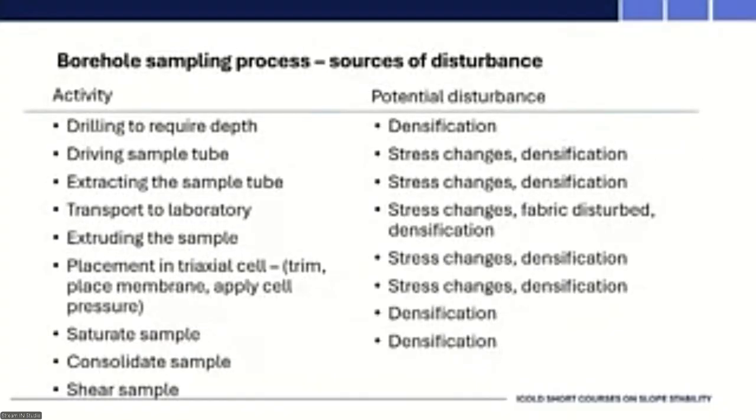The activities that we typically encounter when we have to sample using a borehole drilling technique will be, we are drilling to a certain depth. Hopefully it will be something that is not shaking the entire world around you up too much, but that may cause a little bit of densification of the sample, which is still underneath the bottom of the borehole. Then we are going to drive a sample tube into the ground and invariably shear that sample. We are then going to pull on that sample and hope that the sample comes along, and then we'll transport it to a laboratory. So with all of those actions, there are big stress changes associated, and quite often also quite a lot of densification.